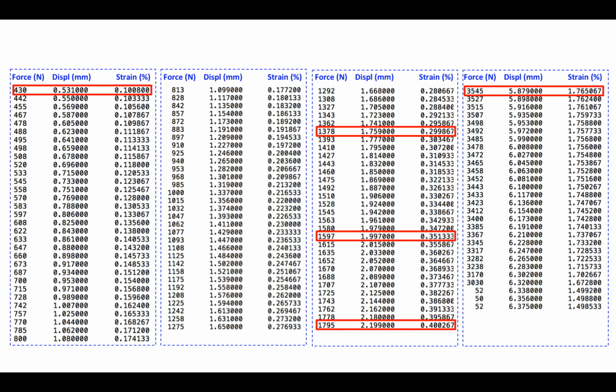So as we continue to stretch the spoke, the recorded force actually starts to go down, and finally at this point here, the spoke can't do anything except just break. It's still true, however, that at 35-45 newtons, our spoke has not yet broken, although it's getting close.